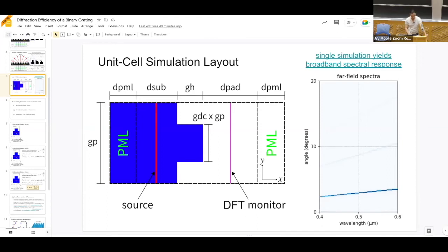Now I have a function that will compute what the reflected and transmitted orders are. There's a single parameter to this function, which is the angle of the incident source. We're going to do this test for both a normally incident source, but also an off-normal incident. This time, the angle is 10.7 degrees, just some arbitrary value, just to demonstrate to you how this works in these 2 cases.